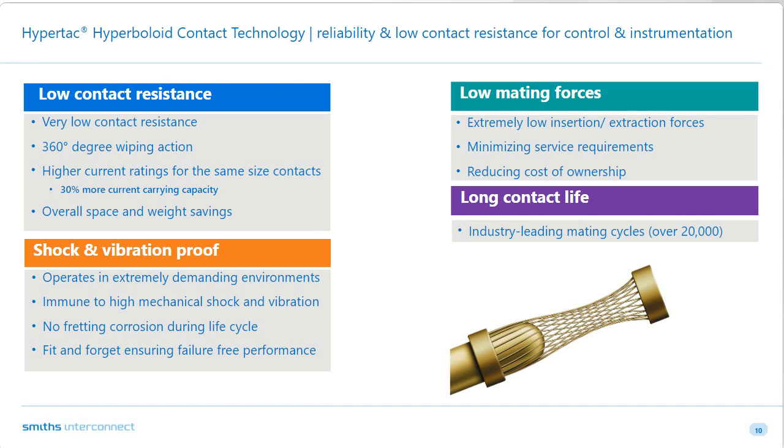kettle. Why? Because firstly, kettles take up a lot of power, and if a lot of scale builds up inside, it takes longer for the water to boil, and the kettle becomes inefficient over time. In the same way, connectors over time develop and increase contact resistance.